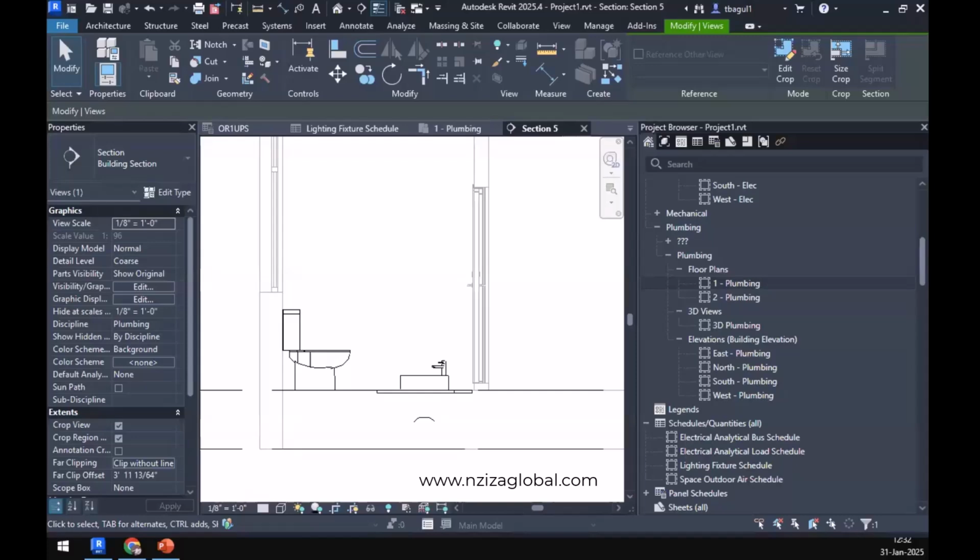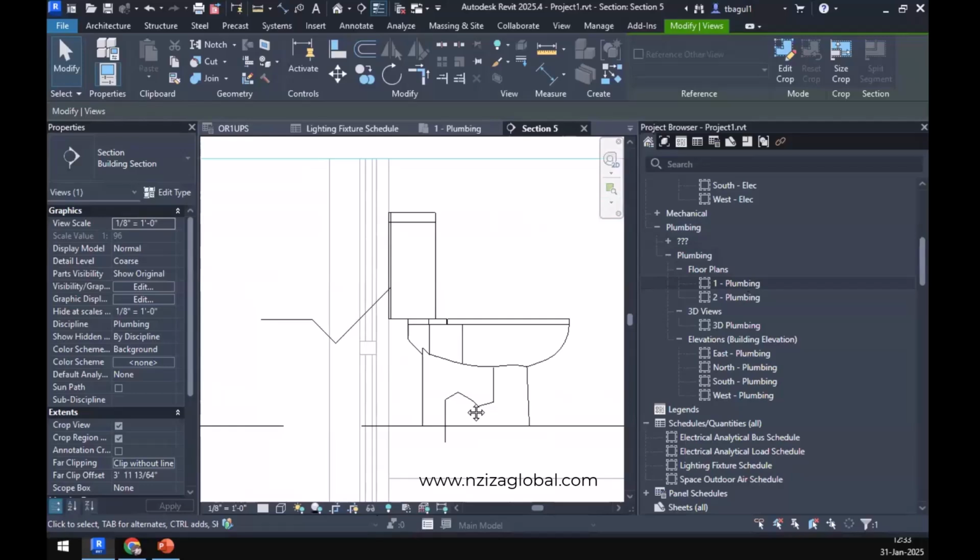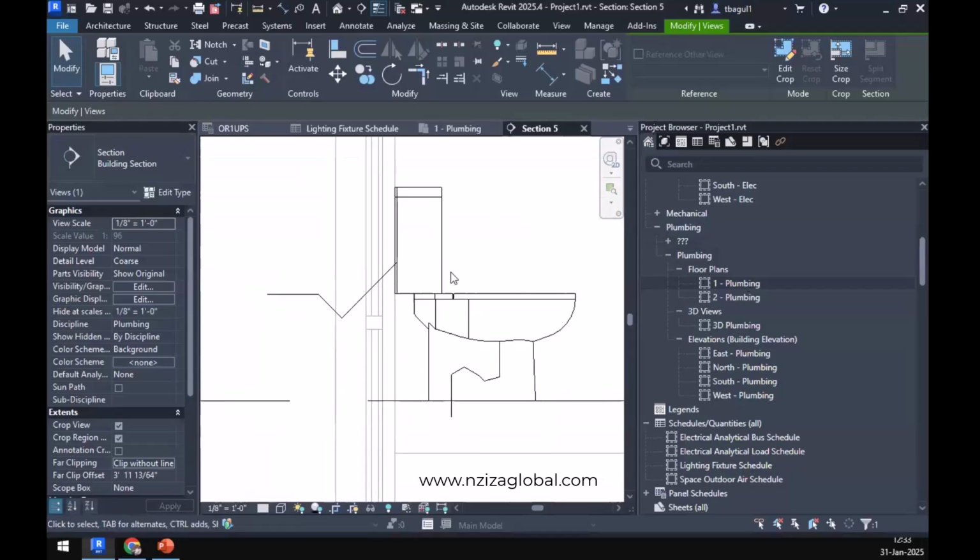Sorry about that, Lawrence and Tony. The point was regarding what type of connections do we use? Do we use a S-trap or a P-trap? So there are two types of water closet. Is it based on floor mount or is it based on wall mount? If it is floor mount, then the possibilities are that you have a S-trap assigned to it. If it is a wall mount, then it might be a S-trap or it might be a P-trap. You'll need to confirm that with what is available in the market and then specify it accordingly.